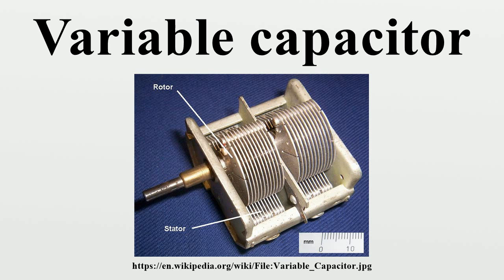Dynamic range is limited by noise rather than large signal handling requirements, and varicaps are commonly used in the signal path. Varicaps are used for frequency modulation of oscillators, and to make high-frequency voltage-controlled oscillators, the core component in phase-locked loop frequency synthesizers that are ubiquitous in modern communications equipment.